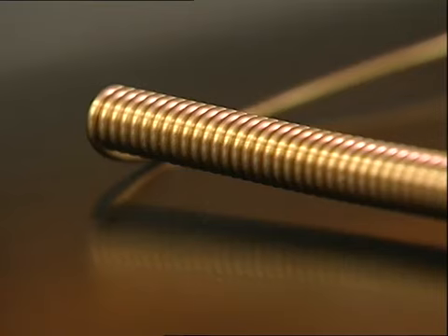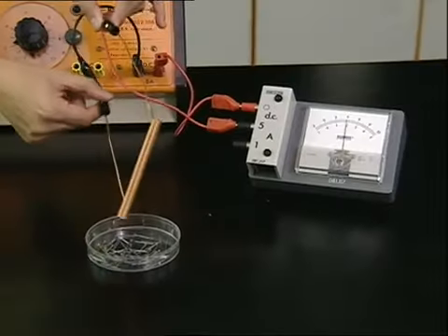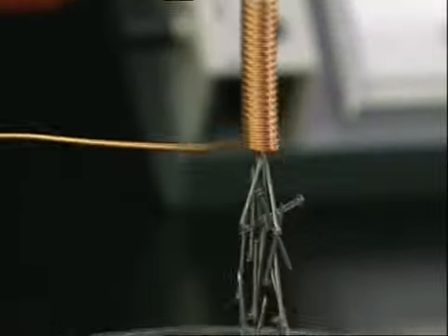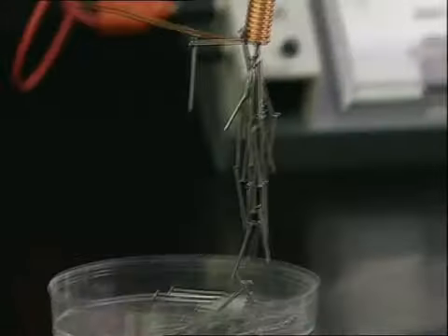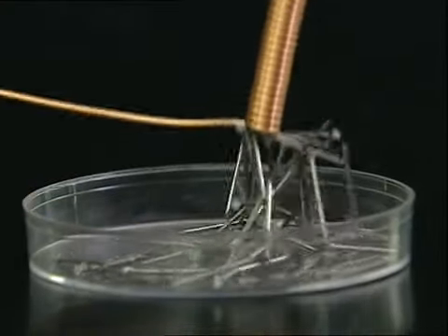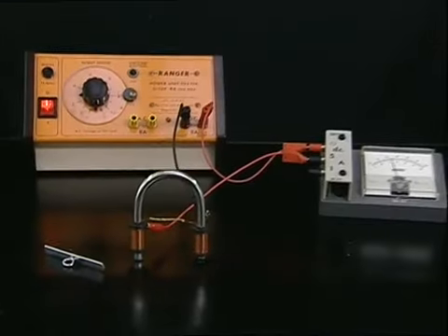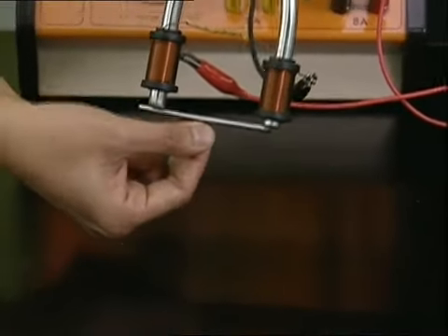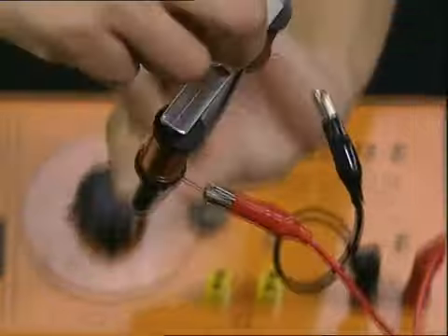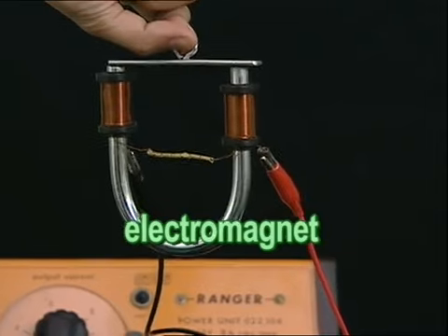When a solenoid is connected to a power supply, it can also attract iron nails. By increasing the current passing through the solenoid, we can see that the solenoid attracts more iron nails. This shows that the stronger the current, the stronger the magnetic field set up by the solenoid. When an electric current passes through a solenoid, a magnetic effect, similar to that of a magnet, is generated. A device that generates a magnetic effect after being connected to a power supply is known as an electromagnet.